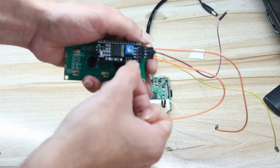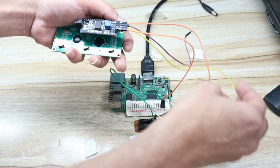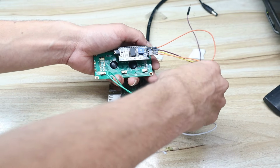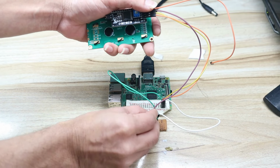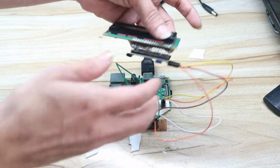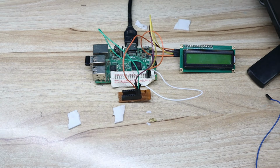Okay, first connect the SCL pin from this I2C module to the 5 number pin of Raspberry Pi. Then the SDA pin from this I2C module you should connect to the 3 number pin of Raspberry Pi. Then after that the VCC pin from this I2C module should be connected to our common VCC point, and the ground pin should be connected to common ground. So a very easy and very simple connection. For detailed understanding of this I2C module, please watch my I2C video. Okay, so once you connect the I2C LCD with Raspberry Pi, now the next connection is this